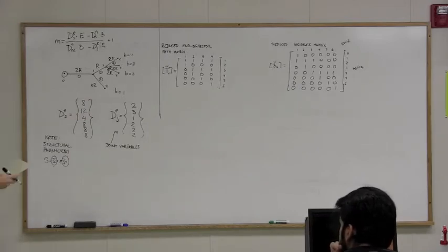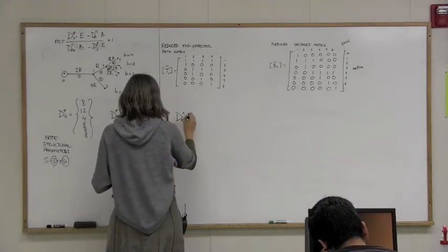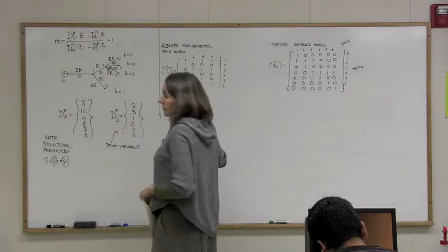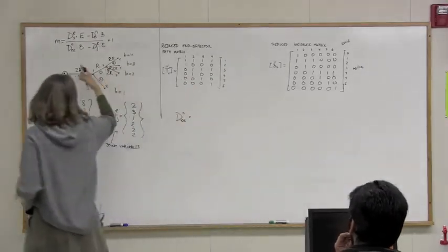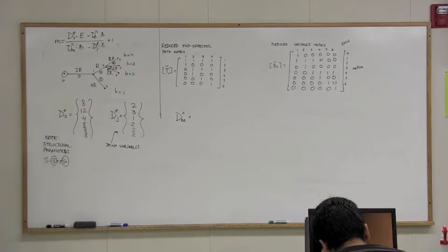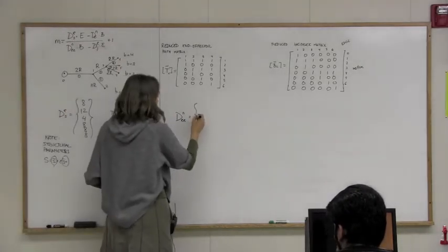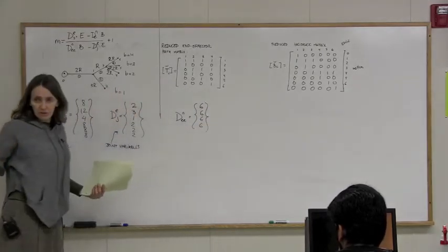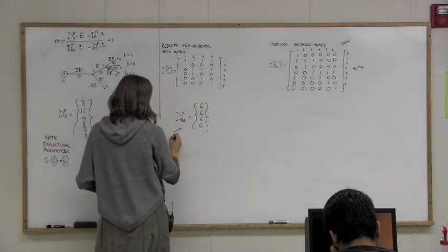All right. Next one, the DEEN. And that we said was the dimension in which each of these end effectors move. These are revolute joints, and we know that as soon as you have one revolute joint, the linkage locus space becomes the whole space, which means that for each of them, this is 6. Each of the fingers moves in our 6 degree of freedom space. We don't have planar fingers, we don't have specific conditions on that. So, the space in which each of the end effectors move.